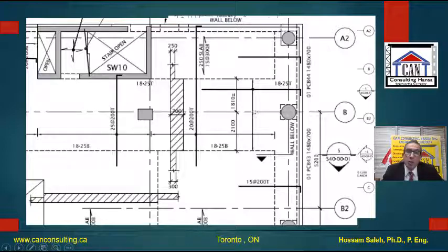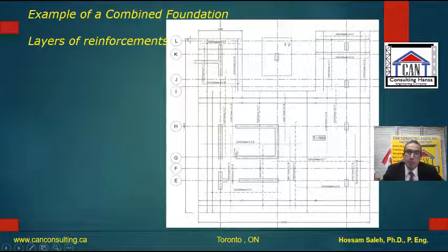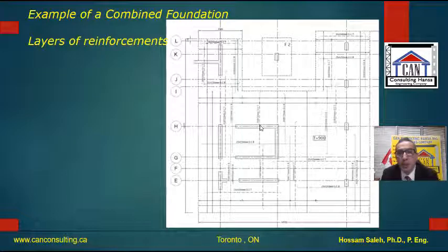So you have to know this bar here, you look at there is also a dot and then the arrow, so that means this beam, this bar will be distributed from this edge to this edge. Now there is another way of distributing the bars in the drawings. As you can see here, you have different parts.